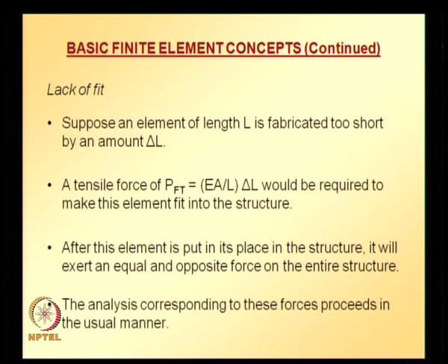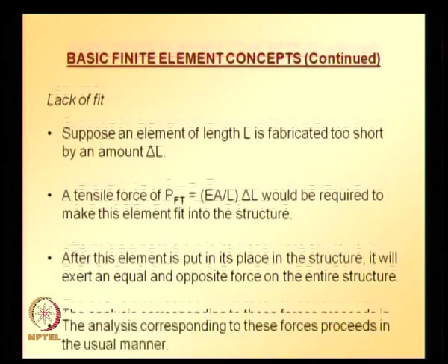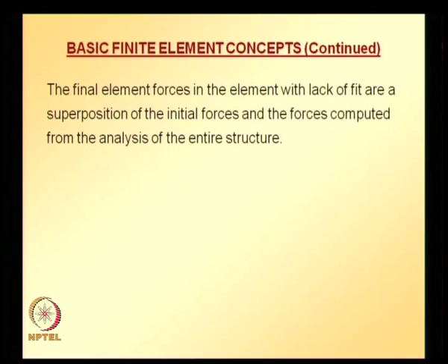So the analysis corresponding to these forces proceeds in the usual manner, except that at the end when we are calculating element forces, we need to add the forces due to lack of fit. The final element forces in the element with lack of fit are a superposition of initial forces and forces computed from analysis of the entire structure.